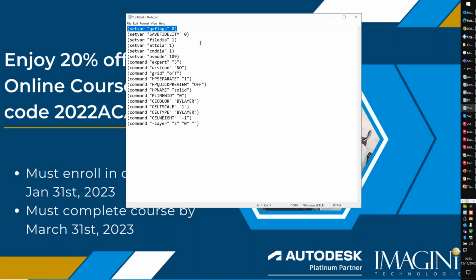And I immediately set my OS mode to 109. This is my preferred object snaps, or my O snaps. I set command expert to 5. Expert is not held, so you have to set that every time. What that does is it suppresses a lot of the muttering that we get from AutoCAD about file already exists, are you sure you want to do that? Or, hey, this object isn't a polyline, do you want to convert it to one? I do a lot of those things. I turn my UCS icon to no origin because I do not like my UCS icon.